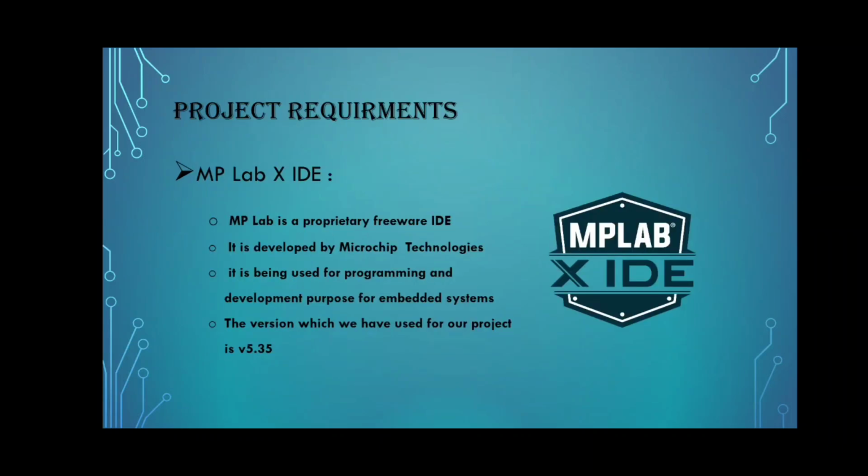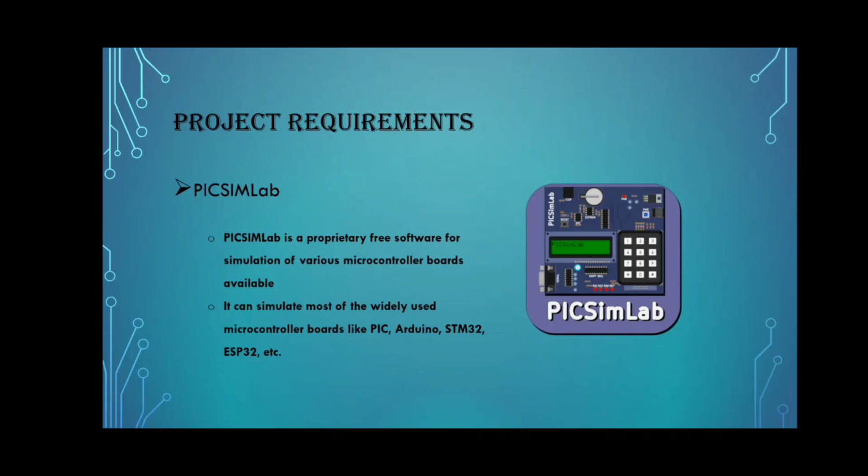Project requirements: MPLAB X IDE. MPLAB is a proprietary freeware IDE developed by Microchip Technologies. It is used for programming and development of embedded systems. The version which we have used in our project is v5.35. PICSIMLAB is a free software for simulation of various microcontroller boards. It can simulate most of the widely used microcontroller boards like PIC, Arduino, STM32, and ESP32, etc.